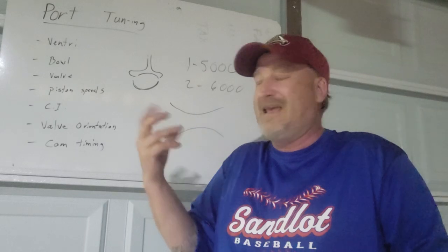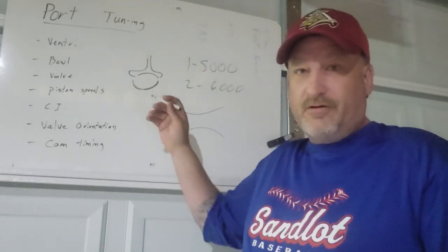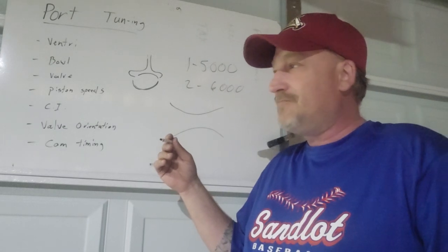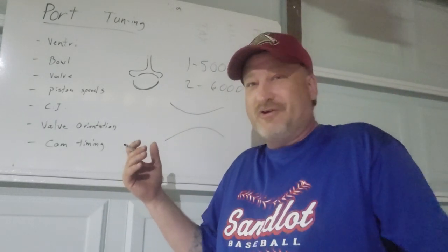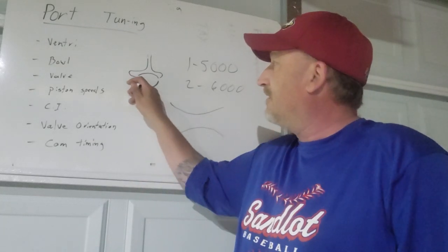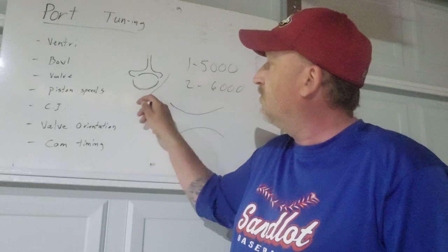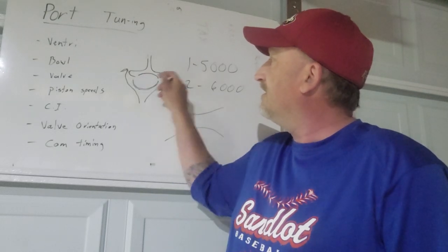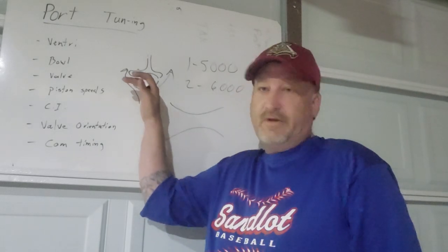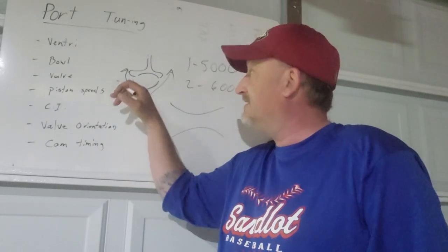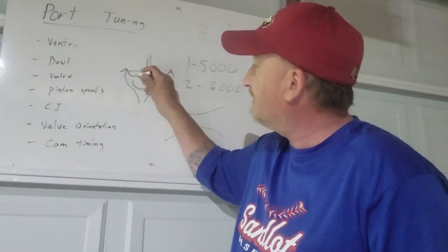Even though it's a compressed gas, it creates a gaseous border. Let's call it a force field. Okay, for some of your truckies or techies out there, it creates a force field to where the exhaust gases are directed more towards the exterior of the exhaust valve without using a mechanical device. It's using the pressure built up in that cup area to create that sphere.